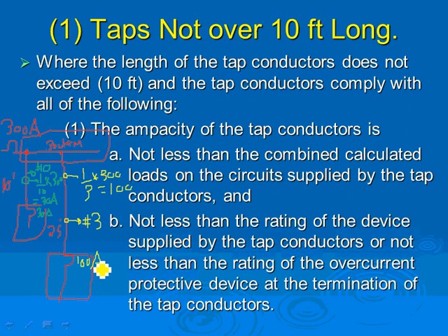By the way, could I land this in the main lugs only? Six breakers or less. Typically we feed it, but it has to land in a circuit breaker that adds up to that density. So technically, I have my disconnect here for the system.